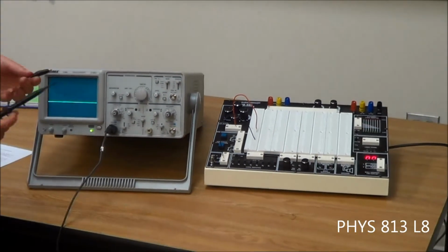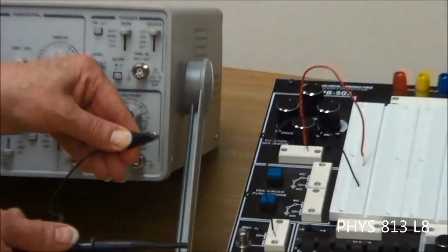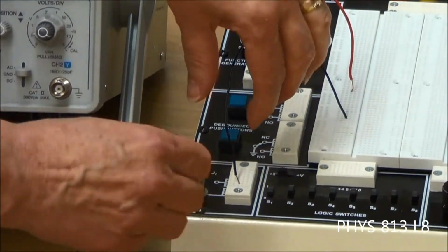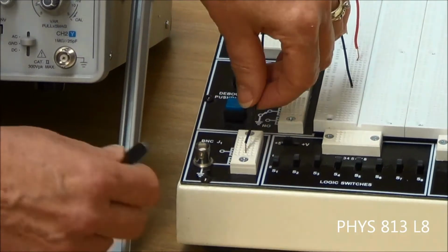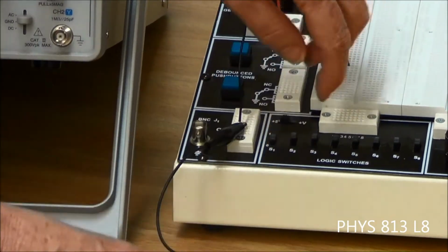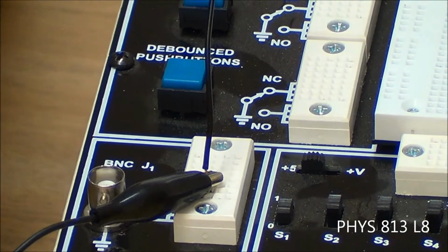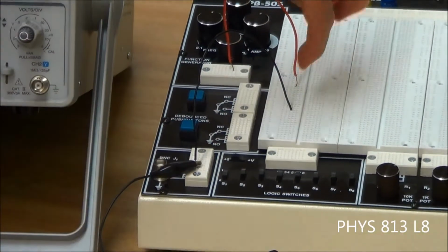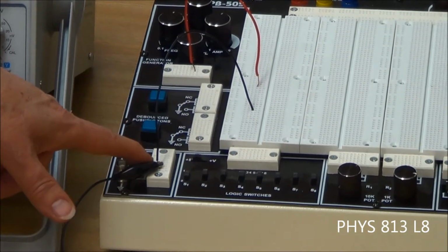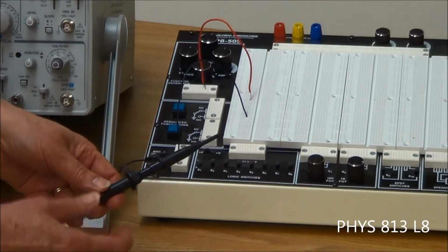Then we need to connect our probe. So we have the ground of our probe, and it always gets connected to the ground of the circuit board. That's no matter what. So you need to make sure that there's enough of the black wire stripped that you can actually connect to the wire part. I could connect it up here, but I want to get in the habit of connecting it down here. We just need to make sure that we connect to ground.